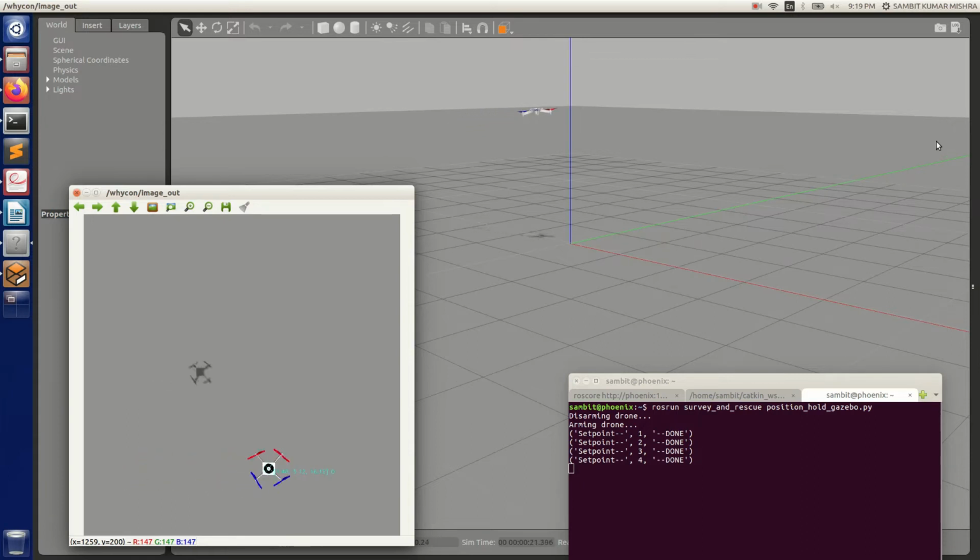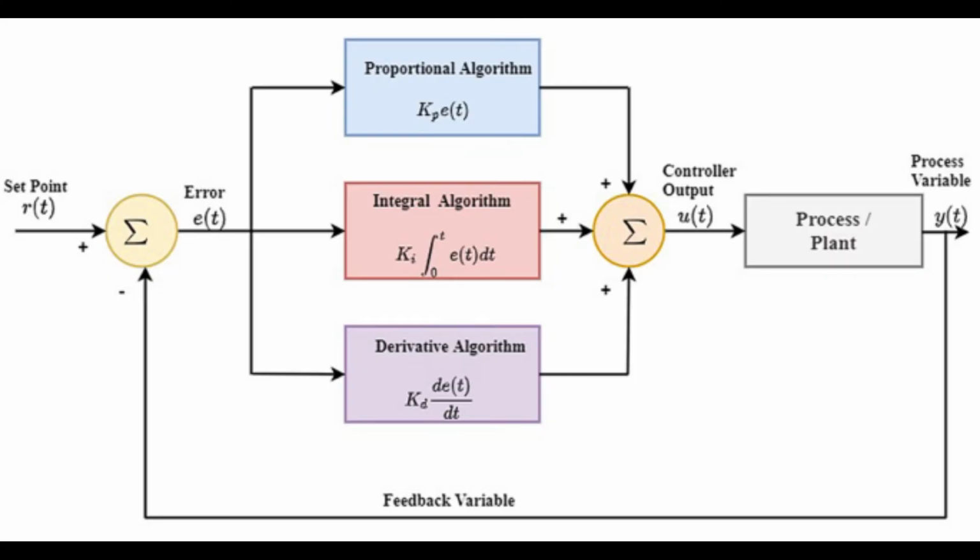This concept can be better understood while looking at the diagram. Now Kp, Ki, and Kd are the coefficients of proportional, integral, and derivative parameters respectively. Varying the values of Kp, Ki, and Kd in a proper way will eventually result in the stabilization of the body, drone in our case, in the system.